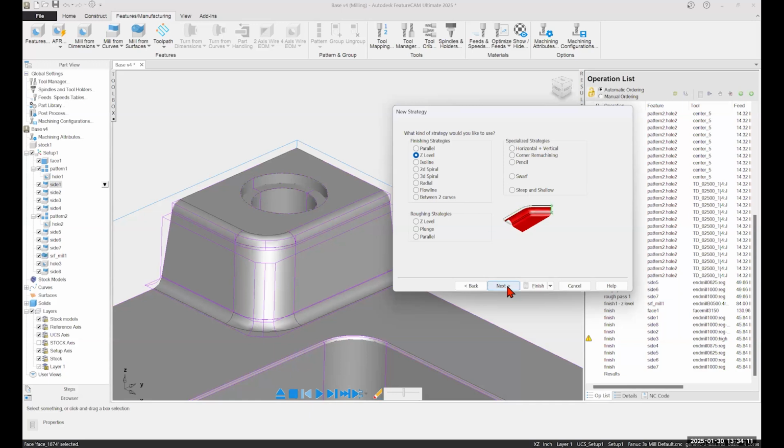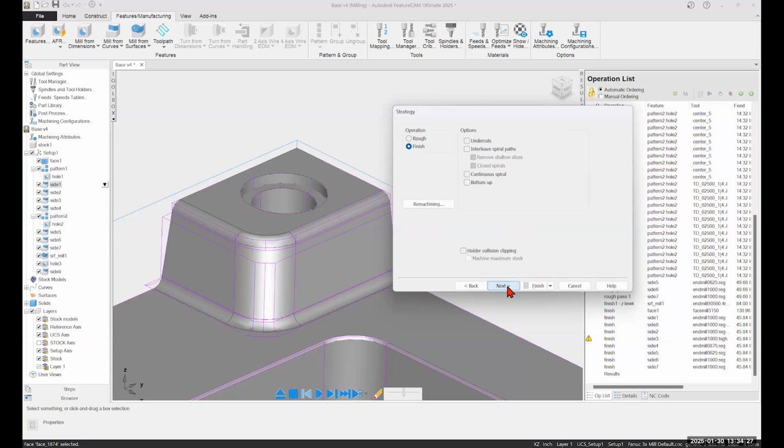The type of toolpath that you select, by the way, is going to be based off, obviously, your preference and how you want to cut it, but also the feature shape, right? If it has undercutting, if it's sloped, if it's a ruled type surface, all that other type of stuff is going to come into effect. Again, we're doing a roughing operation. We can allow for certain things more discreetly within this way of creating this feature, right? So some of the automatic feature recognition actually creates this type of feature, but it will create it without setting some of these more discrete settings.